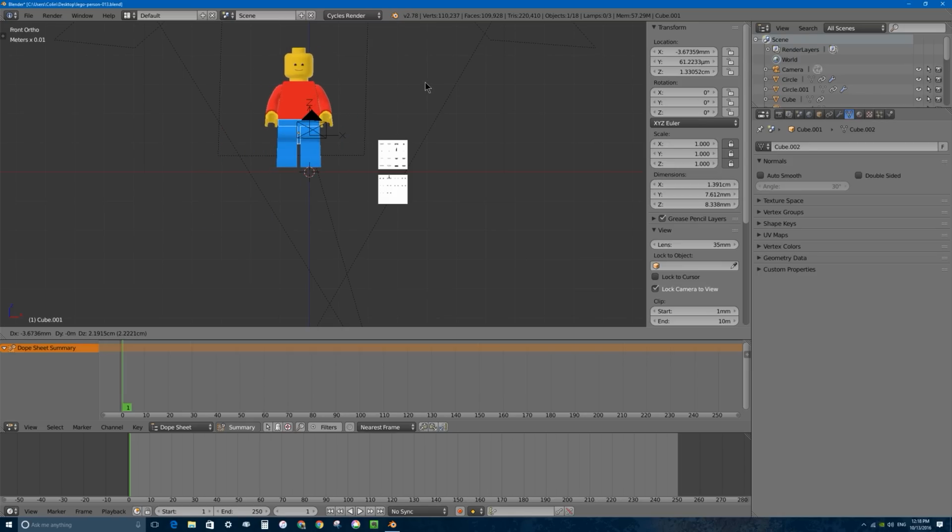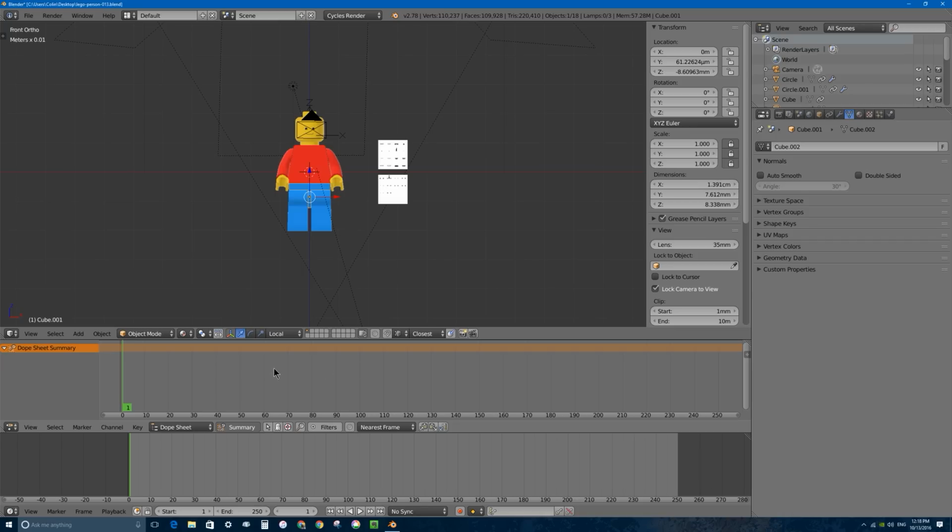They actually plan out their animation ahead of time at a wide scope in terms of a whole scene before they actually start animating. That's what this Dopesheet editor window is based on. You get a wider scope and you can zoom out by dragging on the right side of this scroll bar to get a wider view of your scene, and it shows all the keyframes of all the objects in your scene. So this is basically for making the planning draft, or the key poses, or the rough pass of your animation when you first get started.